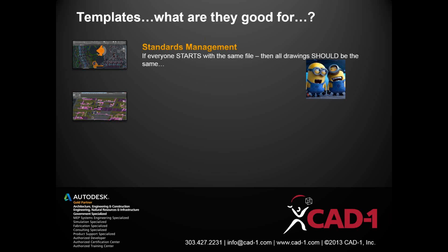Next thing that templates are good for, drawing setup time. If you don't have a template, if you start with a blank template, or what we call the AutoCAD template or the out-of-the-box template, it doesn't have any layers, doesn't have any text styles, doesn't have any settings, any of that kind of stuff, you're going to spend a lot of time every time you want to create a brand new drawing, creating a new layer. Oh, I need to draw some walls, got to create a walls layer. Oh, I need to do this, got to create the layers. Need to draw some text, got to create the styles. So it's going to mitigate all of that drawing setup time.